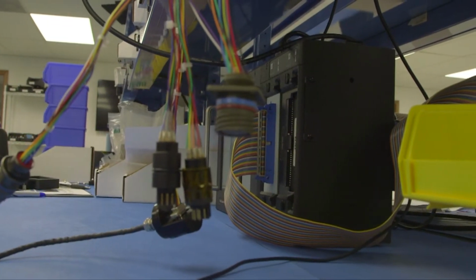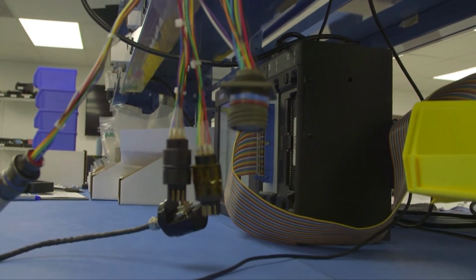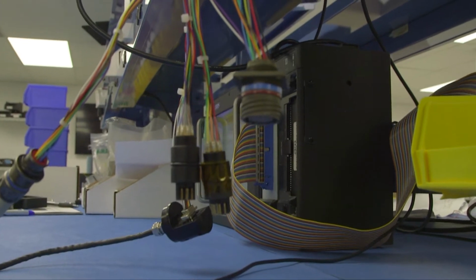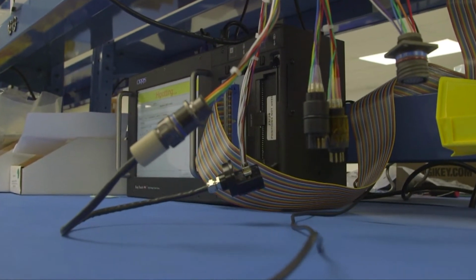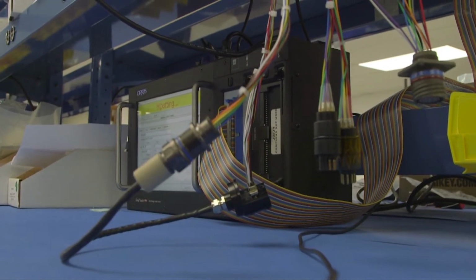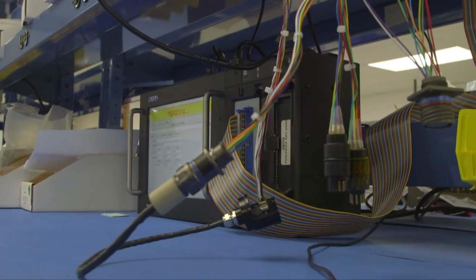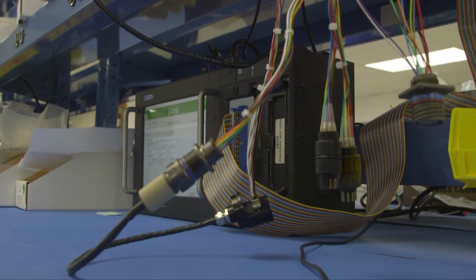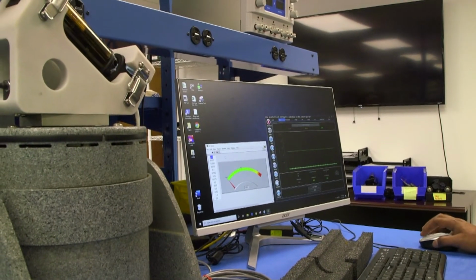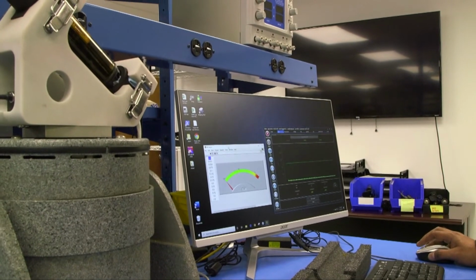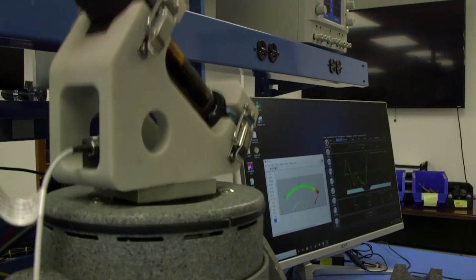All cable harnesses at Rime are rigorously tested using our high voltage hi-pot tester, where cables, their connectivity, and their impedances are checked at voltages between 50 and 1500 volts to ensure low leakage and reliable electrical connections. The electronics is then tested for the sensitivity and behavior of the flow switch using our electrodynamic shaker.